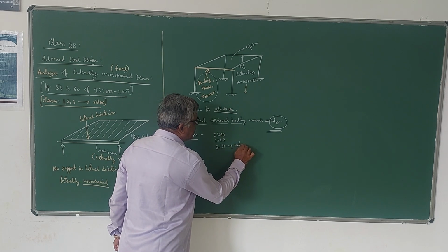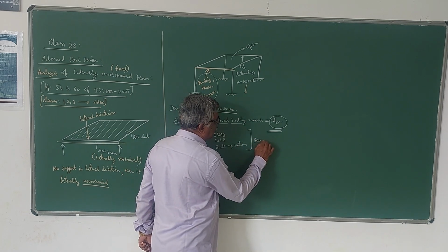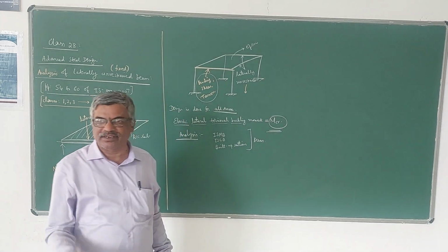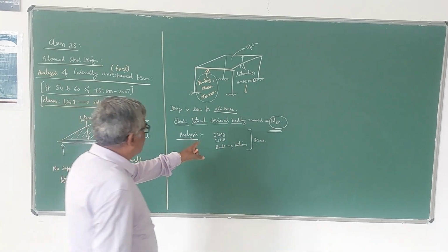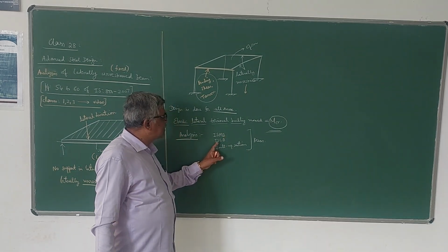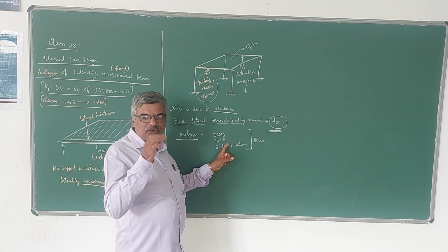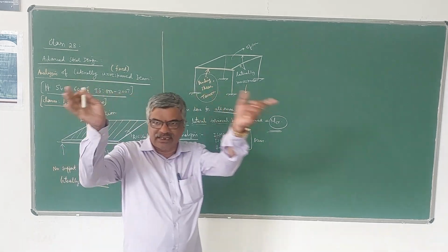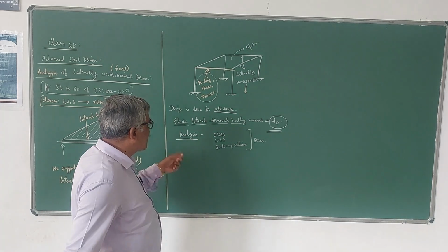These are the sections. Normally we are going to be using beams, whereas in columns we use ISHB sections in steel. Okay? Heavy beam. So this is medium beam, Indian standard medium beam, Indian standard light beam. One more is the Indian standard junior beam. Of course, that junior beam we are using only for purlins in trusses where loads are less. In buildings, you go for this.